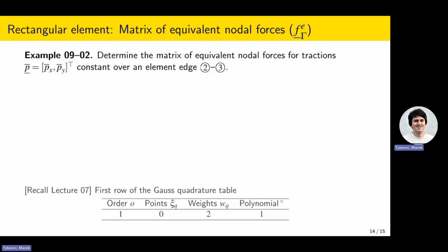And so what remains is actual evaluation of that integral. And again, we can use Gaussian integration or Gaussian quadrature. So we get t and Ly over 2. And now essentially we have 1D Gaussian integration. So we only need to look at the shape functions evaluated at this single point, which will be 1, and for the eta we take 0.